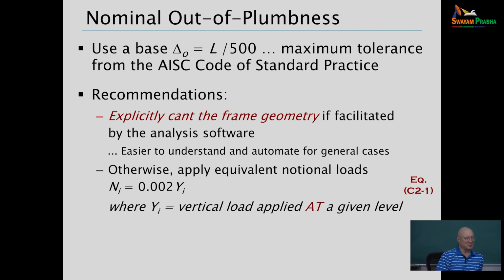The other thing is if they're handling it by loads, well, let me say it the other way. If they were handling it by explicitly changing the geometry, they've got to reformulate, rebuild the stiffness matrix for every geometrical configuration that they want to solve. Whereas if they do it in loads, I've got one analysis where I've built the stiffness equations for the structure, I'm done. Oh, I can put these different notional lateral loads on there so it's a bit faster for them.